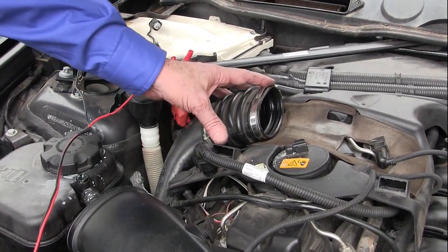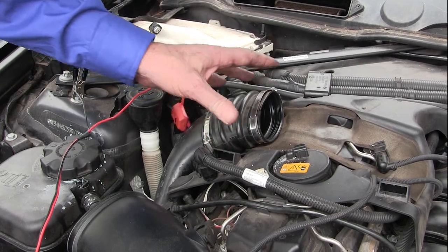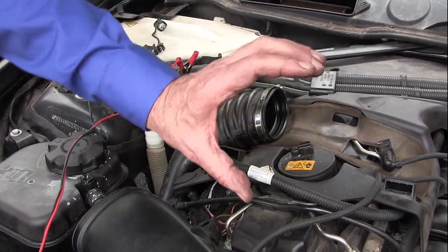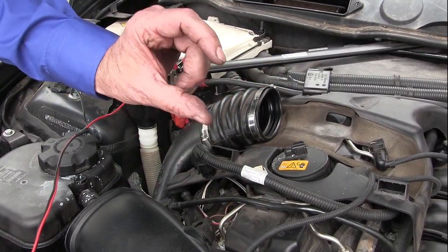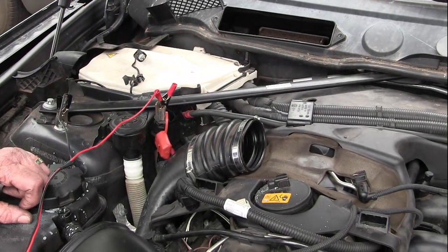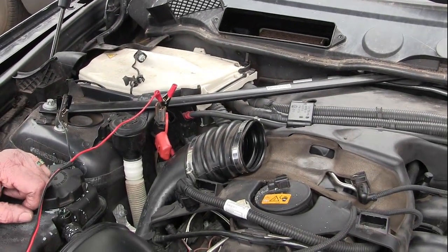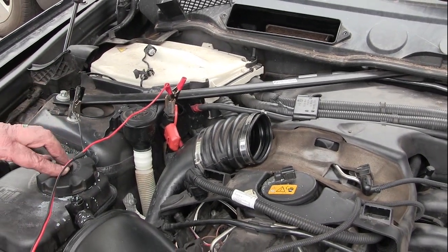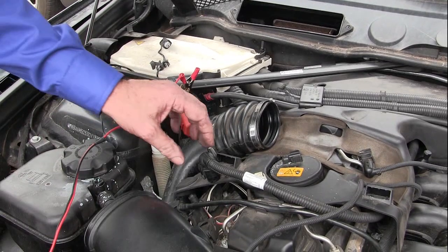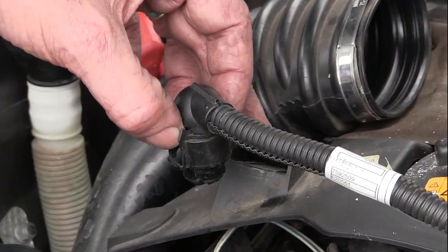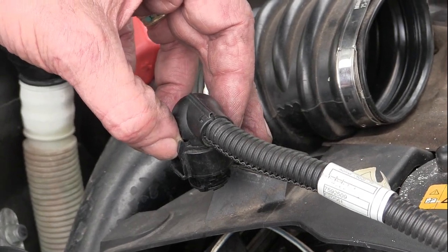Once this Valvetronic is removed from this valve cover, the rocker shaft will default. A spring will move it to where the valve opening is a full 1/2 inch, and now the computer will default by using the throttle plate. That will create vacuum in the intake system, so we now have vacuum to suck the chemical in with. On all of the BMW and Mini products that use Valvetronic, this will have to be removed to have vacuum in the intake system in order to clean the vehicle.